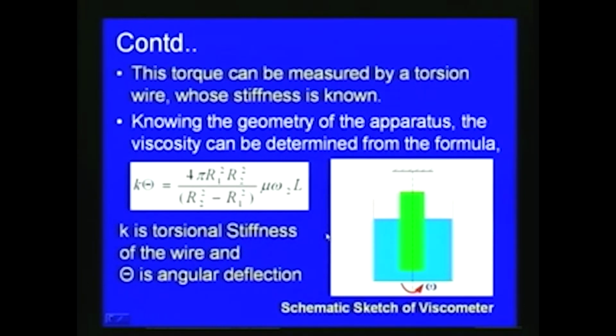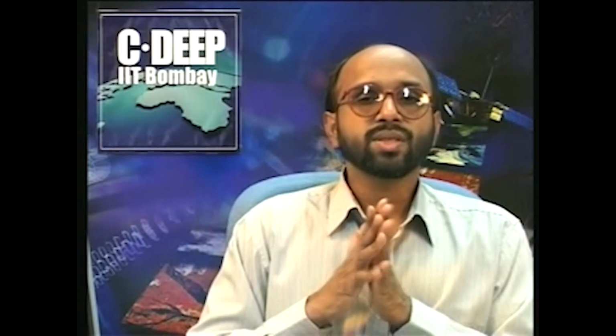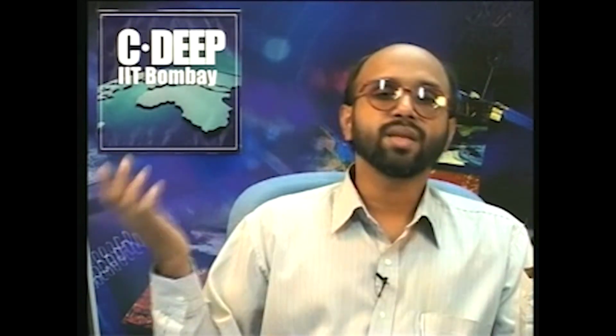So here we applied the equation derived for the flow between two concentric cylinders, and then we got the expression for the velocity and the shear stress and other parameters for these kinds of problem. So this is a typical problem which we started with the Navier-Stokes equation and then simplified the equations, and then we derived the expression for velocity and other parameters. So finally, before closing these exact solutions for Navier-Stokes equation, we will consider one more example.